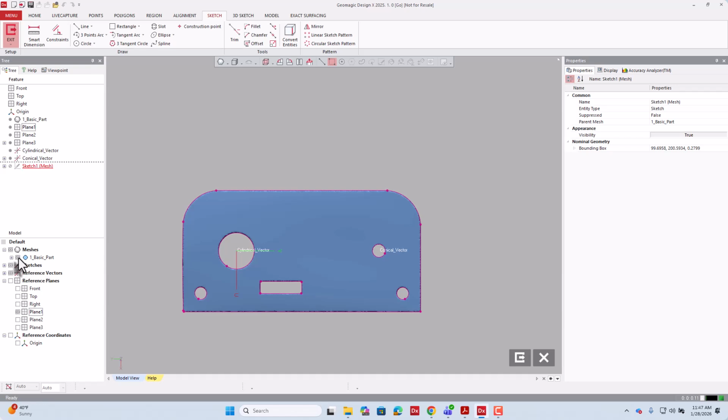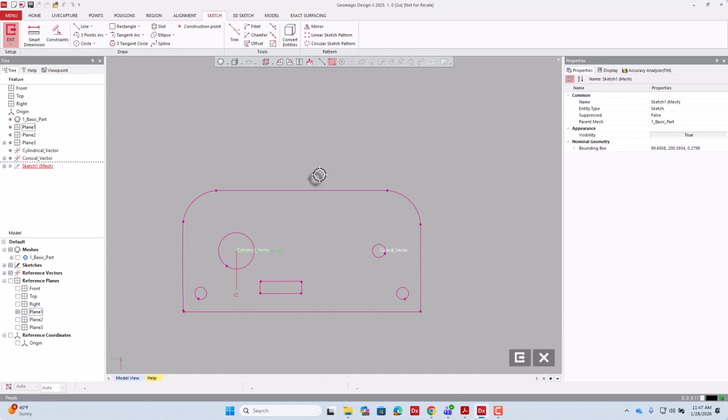You toggle this on, it'll hide the mesh. You toggle it again, it'll show the mesh. So you can hide the mesh and see that there is a pink colored trace. This trace is basically a cross section that goes 2 mm away from the base plane. You took the cross section and it is projected onto the sketch plane. So we get a very crisp cross section of this particular body.